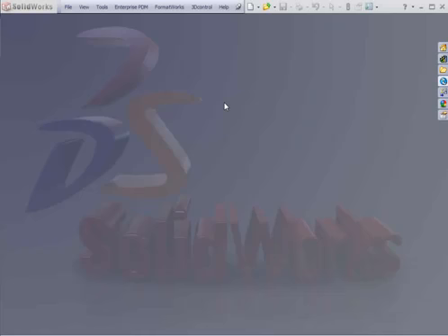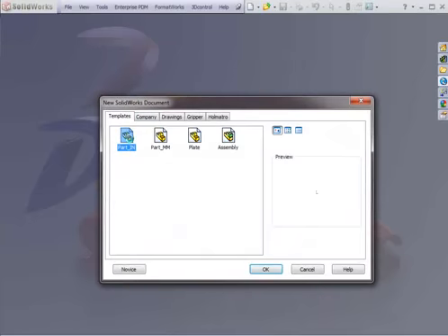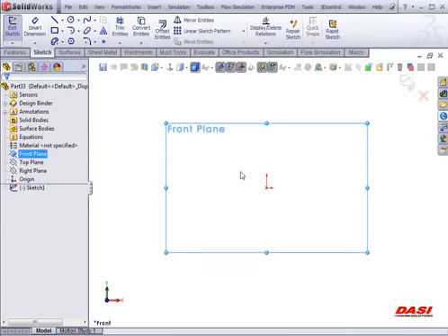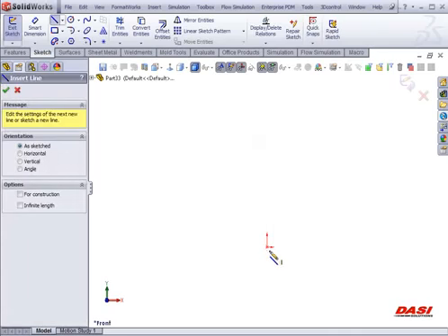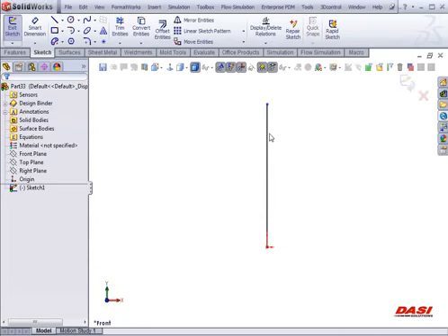During this video, I'd like to demonstrate how to animate springs inside of SOLIDWORKS. I'll begin by making the spring. This functionality has been in the software for a number of years now. When you make your springs, you don't have to create a helix anymore. You can simply make a straight line for the path and the spring. And I'm going to leave this one underdefined for the length.